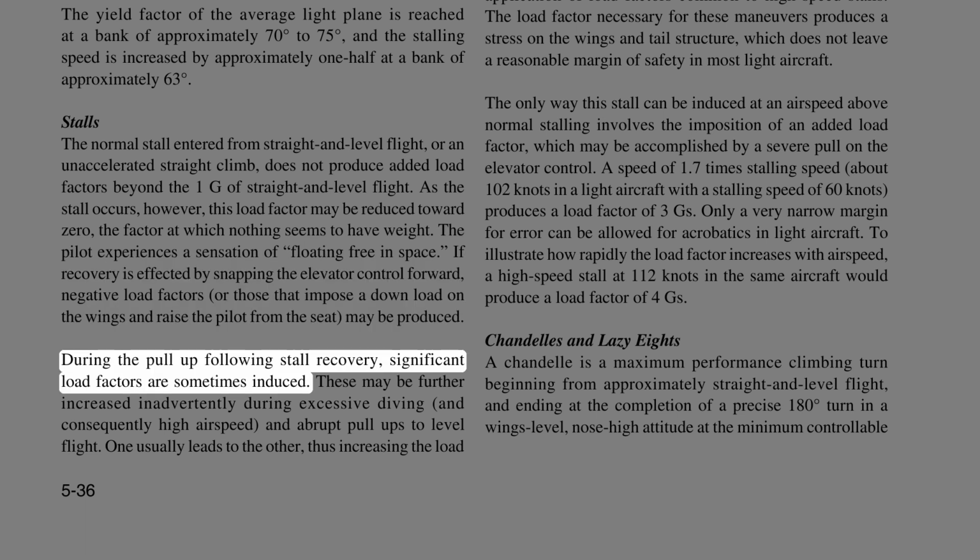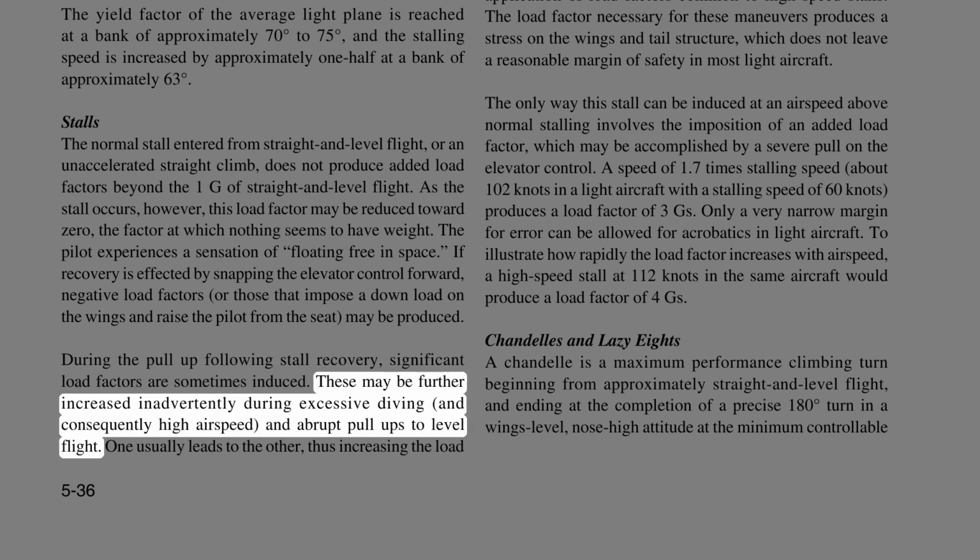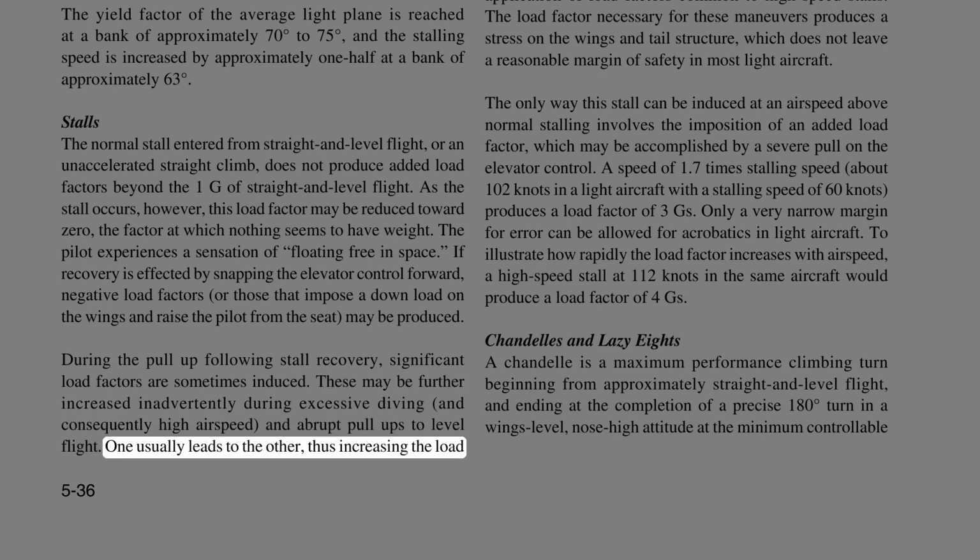During the pull-up following stall recovery, significant load factors are sometimes induced. These may be further increased inadvertently during excessive diving, and consequently high airspeed, and abrupt pull-ups to level flight. One usually leads to the other, thus increasing the load factor.